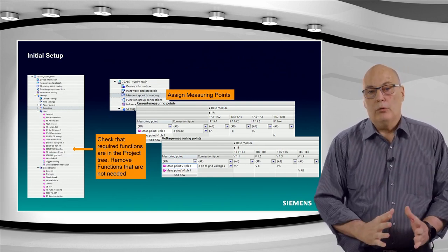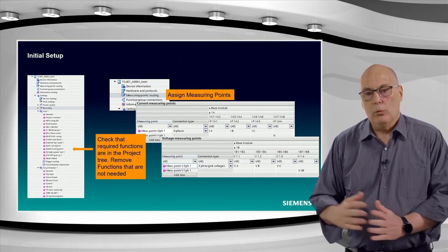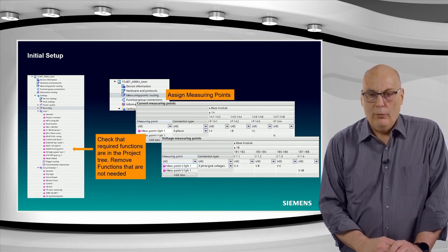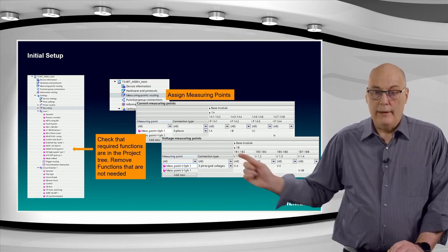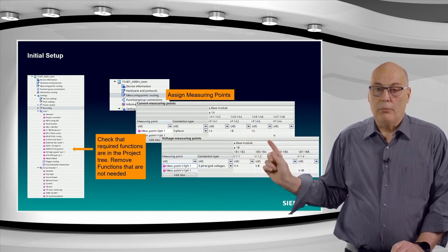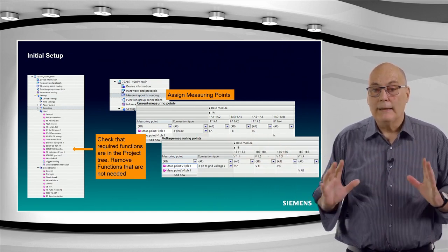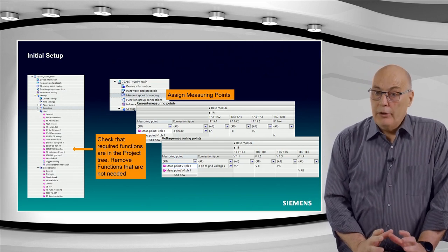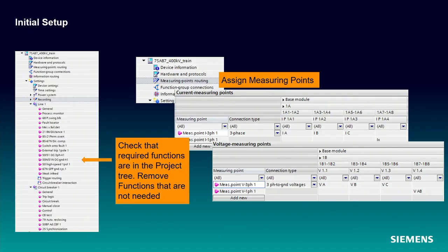And as mentioned at the beginning, we want to look at parallel line compensation. So if we're going to apply the parallel line compensation, we also have to measure the ground fault or residual current from the parallel line. That's what the second measuring point is for, a single-phase current measuring point, applied at the moment just as IX. You don't know yet that it's the parallel line. It is just a measuring point at this point. It is nothing more than that, right?